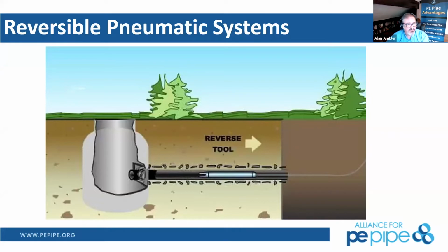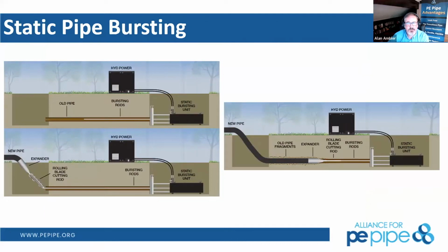If it is intended for the manholes to be removed as part of your project, sometimes we pipe burst first and then remove that manhole to replace it, as the compaction around that manhole is going to be strong before that manhole is replaced, and we'll burst right into that manhole. We'll talk about manhole preparation here in a little bit as well, for what's necessary for it.